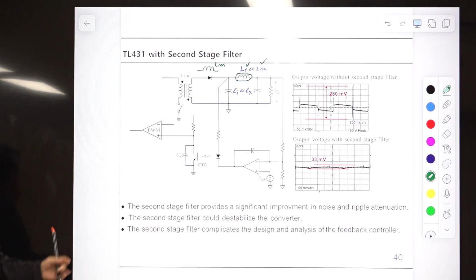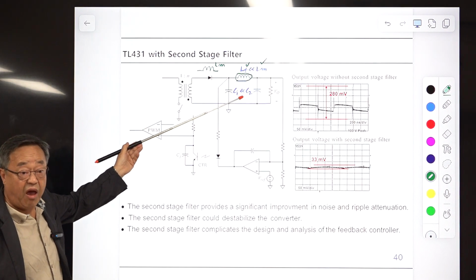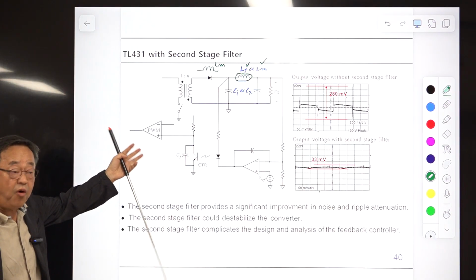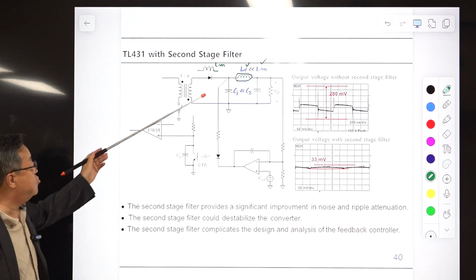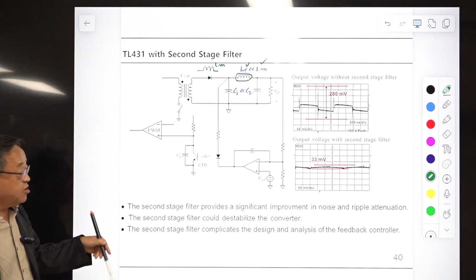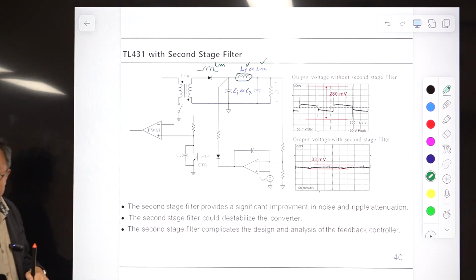Okay, sometimes if you use some long wire, there is this LF. Okay, so LF is already there. Okay, you can make use of it. Otherwise, it works as a noise source. But if you make use of it, you are using a two-stage filter to knock out this spike and this ripple component.